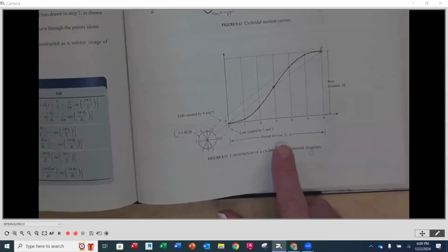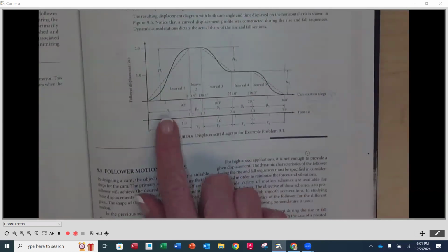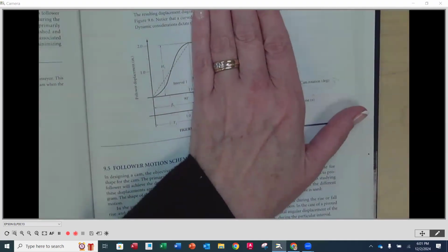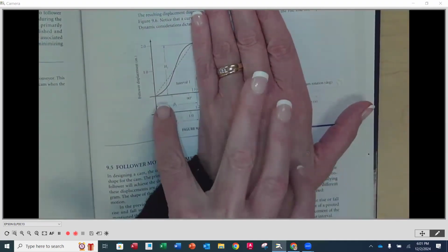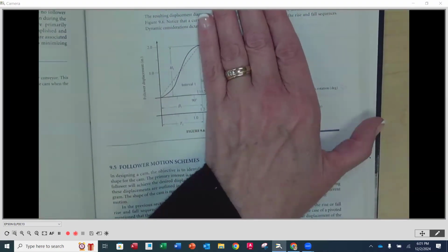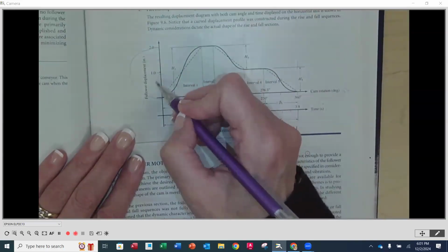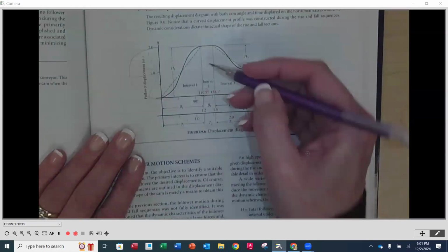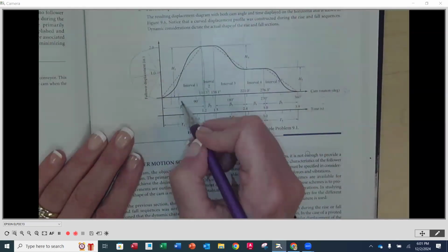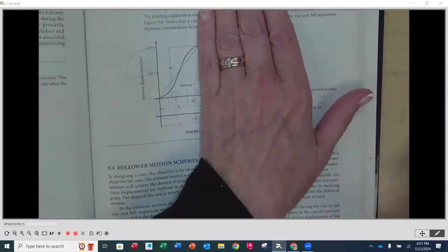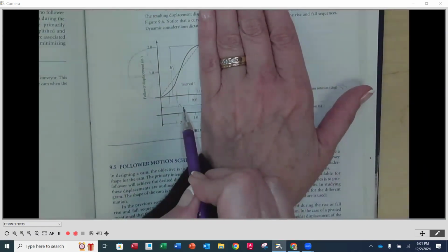No, just this area. So whatever the prescribed motion is, notice that this says either the total time or the beta for that corresponding section. If we remember back on our example problem, we had 5 different betas. So we're just looking at one of these sections here, and we're going to divide this into 6. Does that make sense? So if I do a harmonic motion on this side right here, I divide this into 6 sections, right? And for this section right here, this would be in 6 sections. I would just work with whatever that prescribed motion was, that one beta.